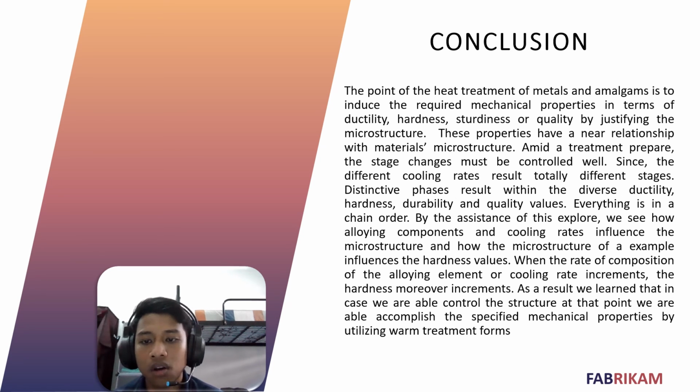By the assistance of this experiment, we see how alloying elements and cooling rate influence the microstructure and how the microstructure of a sample influences the hardness value. When the composition of the alloying element or the cooling rate increases, the hardness also increases. As a result, we learn that if we are able to control the structure.